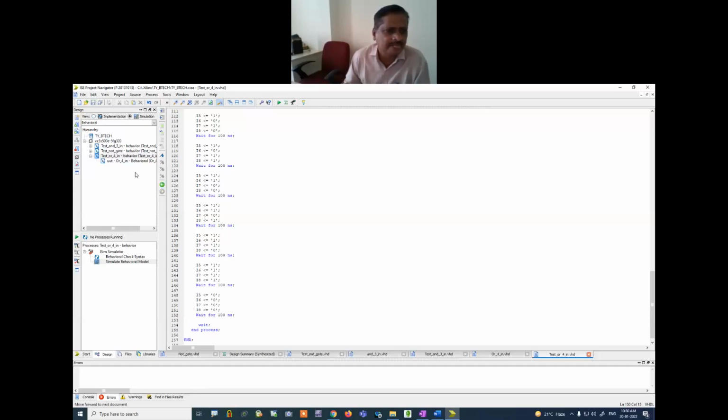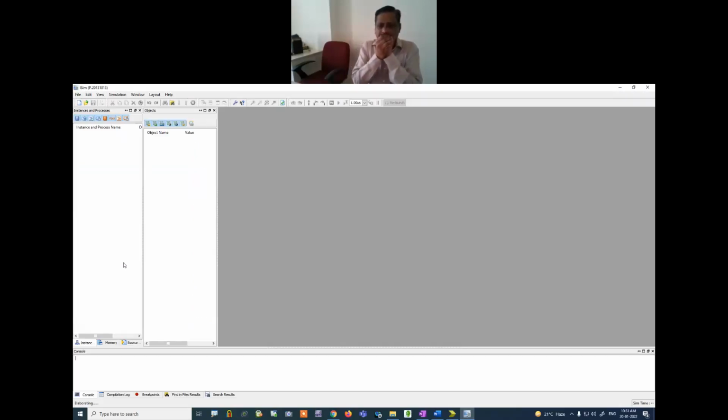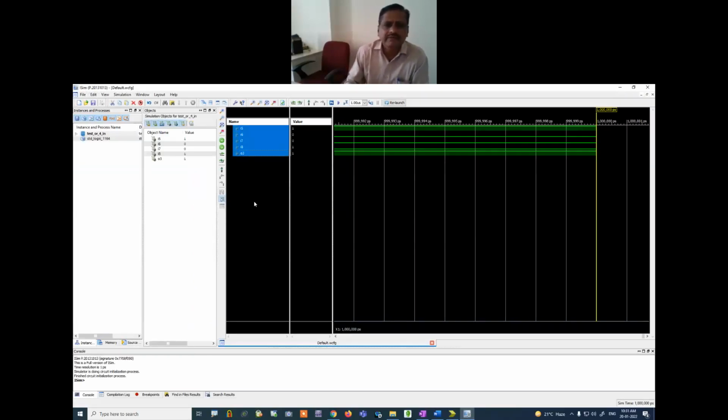We saved it. Now put the cursor on this test bench file and double click on simulate behavioral model. I am double clicking on it, and we are able to simulate the behavioral model. I will minimize it, and then I am in a better position to show you your inputs and outputs.